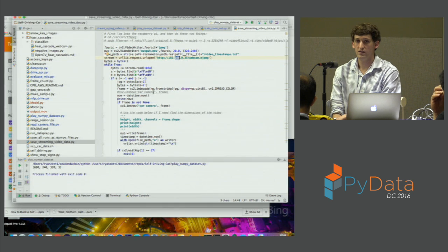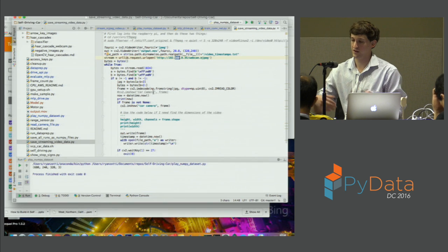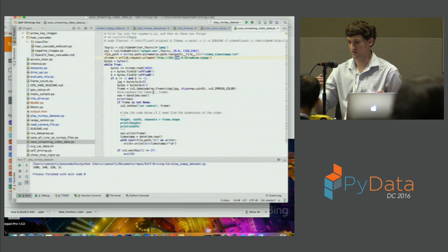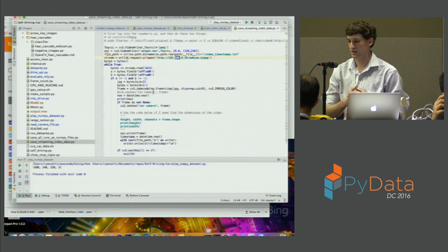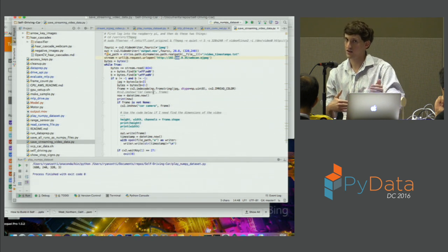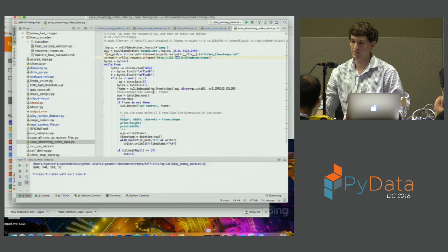Will you be throwing away any image in which the car just paused, basically? No, so that's something I maybe should have changed. My car does overcorrect sometimes, and that's probably because the car is actually coasting sometimes, but when I pass in the data to the model, I never tell it that it's coasting. I say that this command was always on this entire time. So in hindsight, that might be why it overcorrects, because it should coast more than I'm telling it it's coasting.